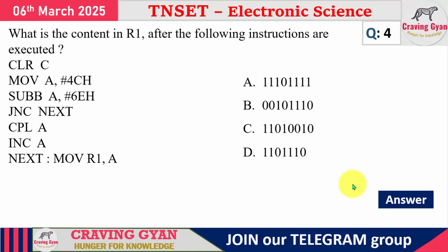In the fourth question, what is the content of the register R1 after executing the following instruction? Clear C. Clear C is nothing but clearing the contents of the carry flag. Then the value of register A will be loaded with immediate data, that is 4CH. Then again you subtract 6EH from it. Then you check the carry flag contents.